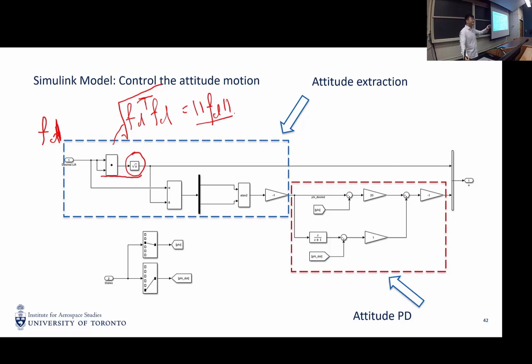So it's like the actual lift produced by the 4 rotors. And then we divide FD by the magnitude of itself, and we get the ND. So this is a normalized vector. So basically it tells you where the quadrotor should point.